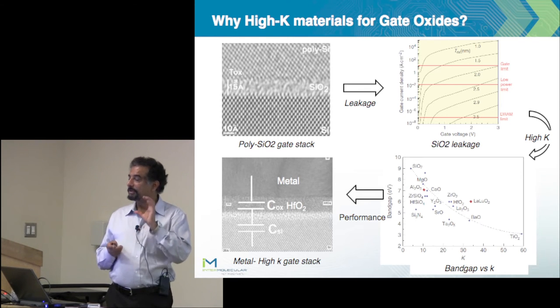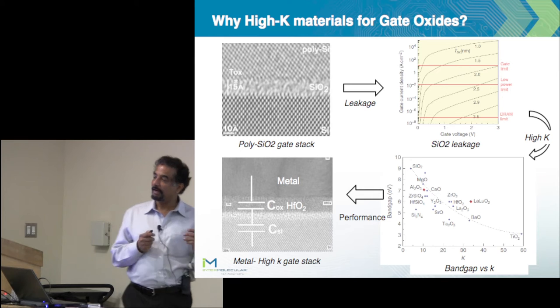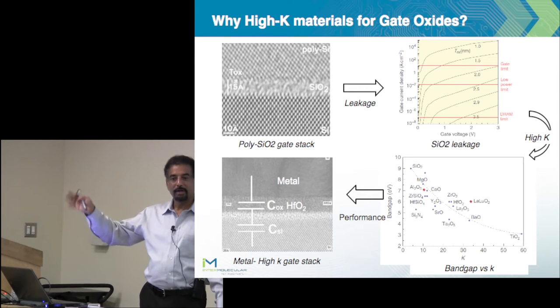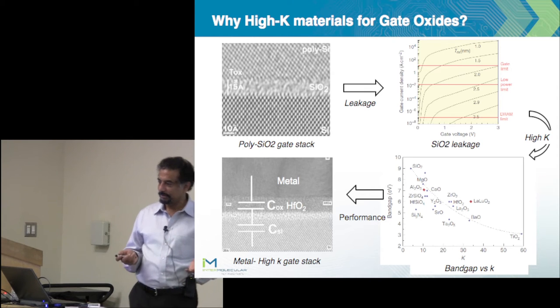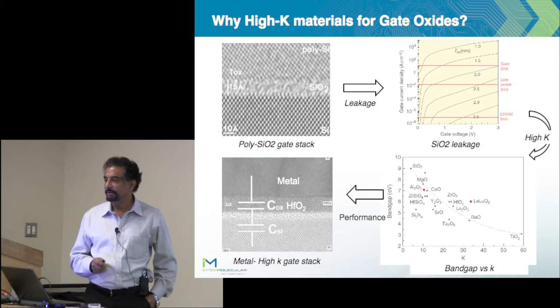And as you decrease the band gap, you reduce the barrier to silicon, so now electrons from the silicon can hop over the barrier, go into the oxide, and then onto the electrode. So your leakage again increases, not because of tunneling, but because you can't maintain enough barrier.